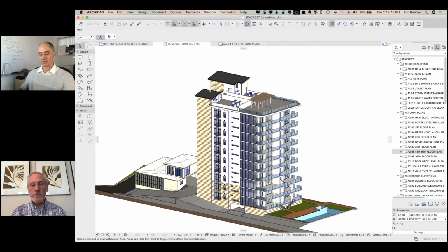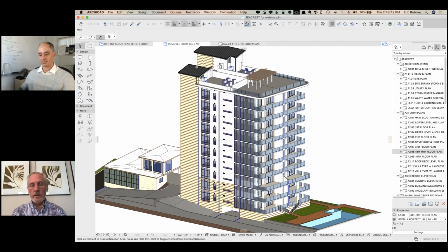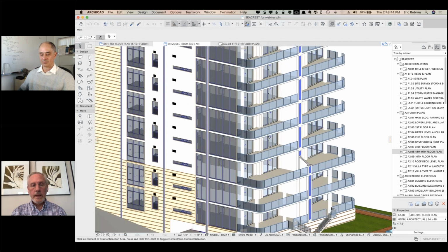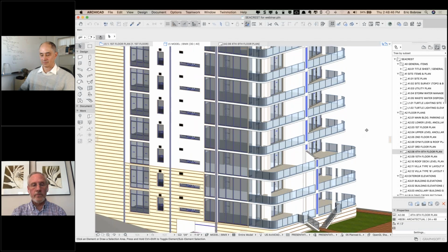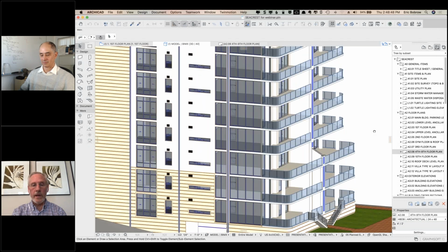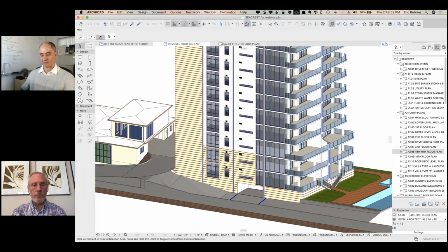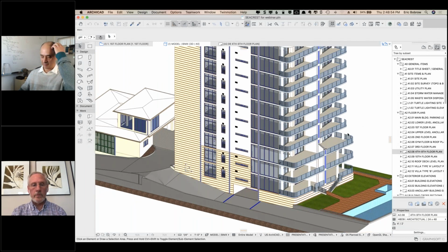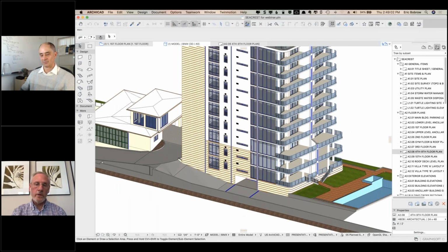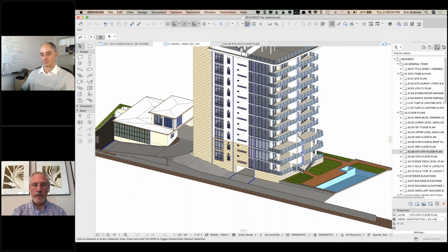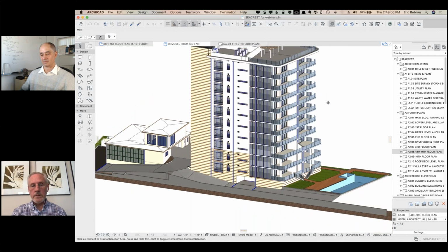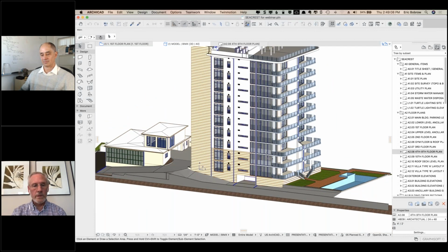So it's a very tight piece of property to develop. It's basically 100 feet wide. One of the requirements is that you have to have 20-foot side yards for fire access. That leaves you roughly 60 feet of building width, which is what it is. So we have two apartments per floor, and they're both outside units, which is nice because you can have glass on 2 sides, actually 3, because we have some on the walkway side.